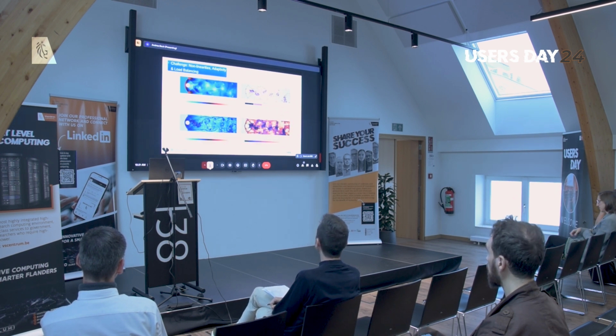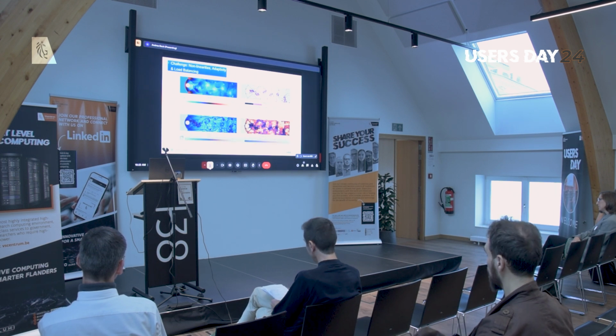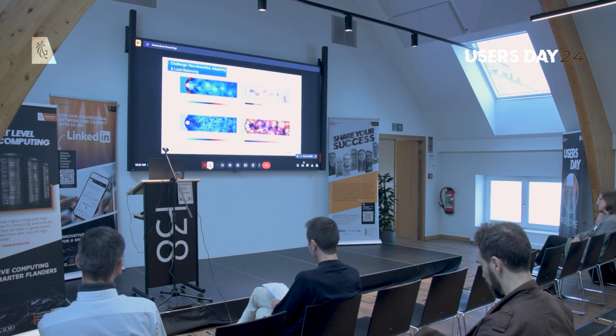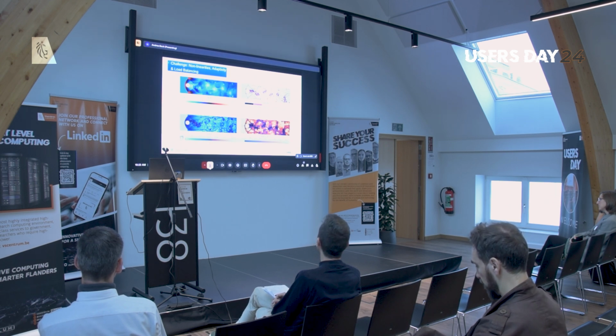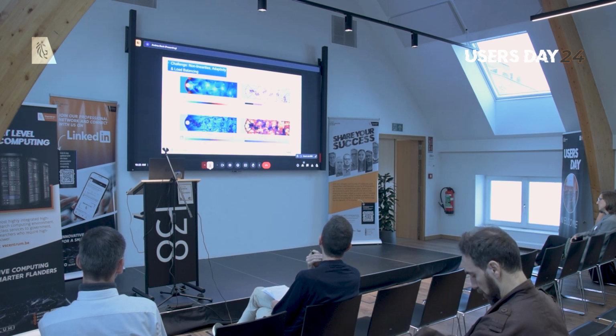Maybe for you just to have in the back of your mind, if you want to resolve different physical entities like shockwave, turbulence, vortices, you need to tailor your numerical scheme specifically for that physical phenomenon. So the numerical discretization should fit or respect maybe the physical phenomenon you are capturing, all of its properties as best as it can. So adaptation of the discretization to the physics is one key. And the second challenge is, of course, how do we do this on an HPC system? So how do we load balance the different adaptive discretization operators to make it an efficient scaler? So this is what you can see on here, different loads of different elements per processor that we distribute as my discretization operator here adapts.